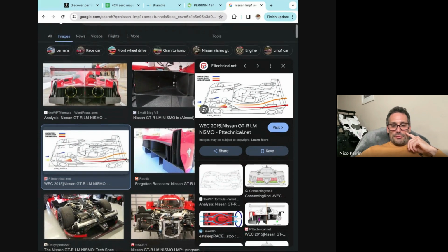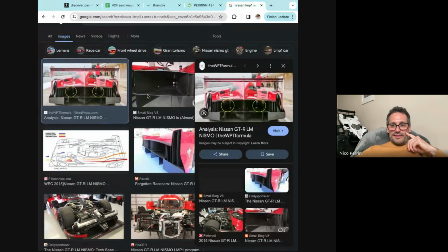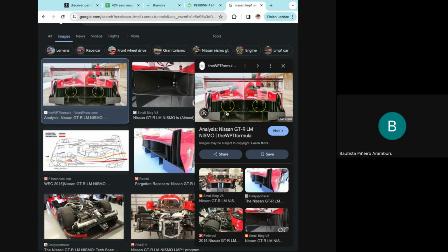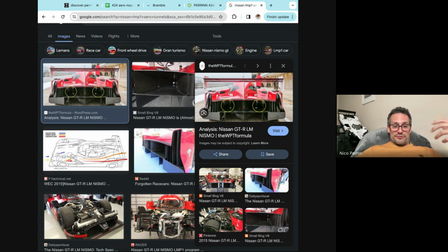pictures here. The problem is, where do you put the suspension? The suspension has to go through. So then they designed a suspension that was extremely unconventional, quite heavy. So the legs would be either side of that. And it meant that the car was extremely heavy. Obviously, they had the front engine concept because they thought you can create more front downforce than rear downforce on these sort of cars. Anyway, there were all sorts of flaws from the conceptual point of view, which, by the way, I could go on and on.